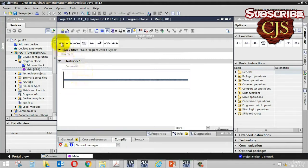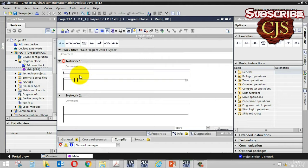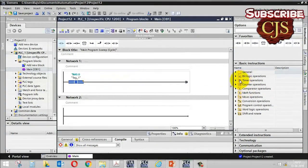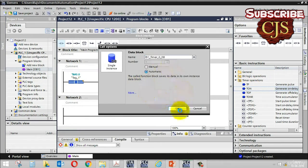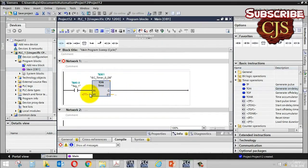Here you can write your sample program. So let me use an input bit. I'm using M0.0, and I will take a timer to actuate an output. So I'm using an on delay timer. You have to program just the way you program in the real PLC. There's no difference. I'll put 5 seconds, and ET I don't want. In the output, I will take Q0.0. Okay, so this is my program.